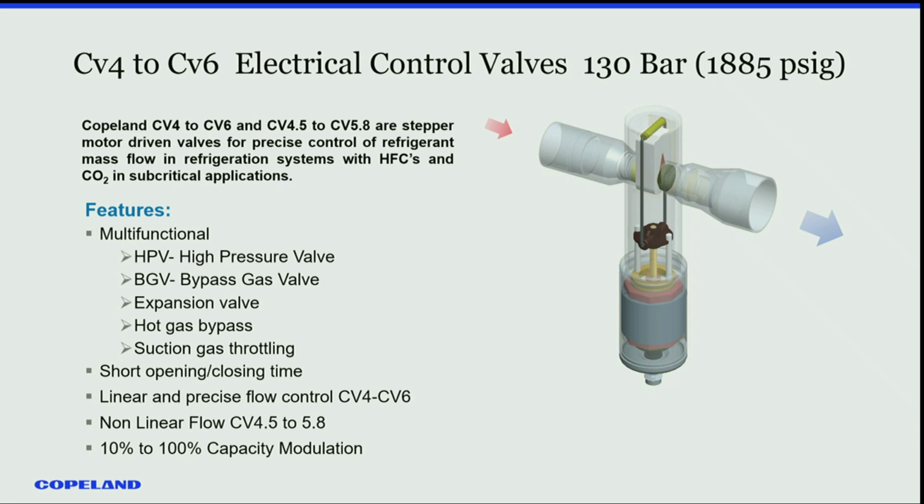We've just launched another version of this valve, which is a non-linear curve, so that you have more smaller steps of graduation at the bottom end. So if you're around that 15, 20% open range, you've got less capacity change per step than the other valve. So you can have tighter control on the low end, is really the point.